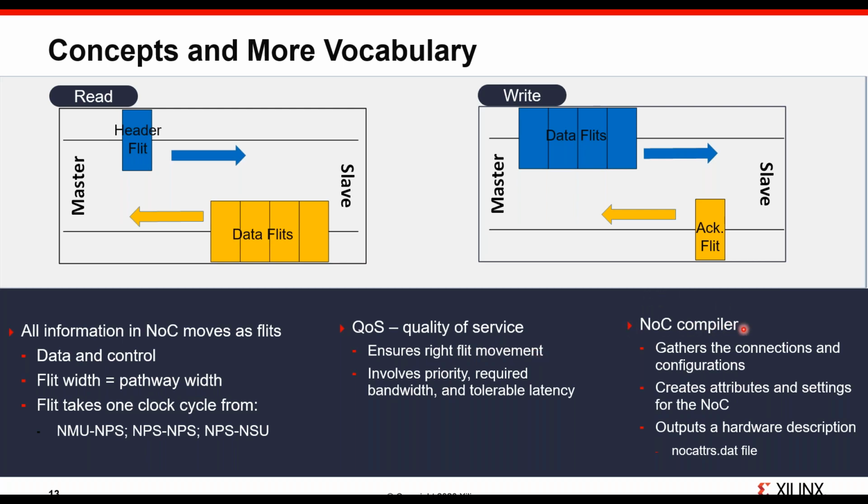And there's also the compiler, which is part of the IPI discussed already. That's what gathers the connections and the configurations of what the designer wants. And then based on what the designer describes to it, just like it does in FPGA or other things that we do as design, it gathers the connections, configurations, and creates these attributes and settings for the NoC. And remember, the NoC is a hardened macro. It's not that some of this is here now and some of it's not because I'm not using it. It's there. It's how you use it.